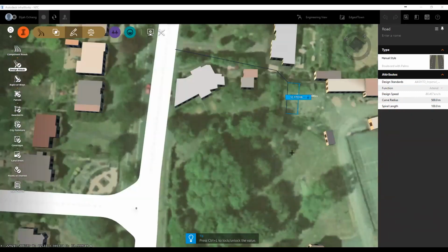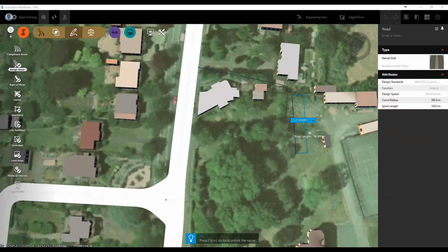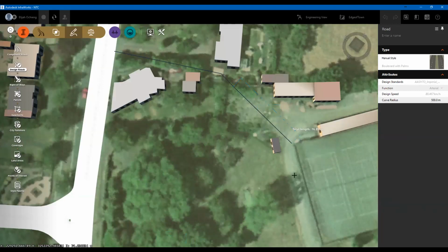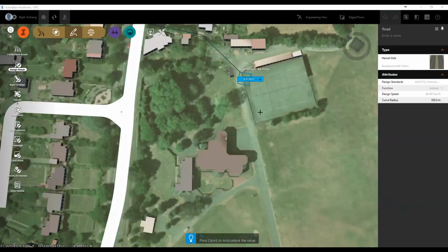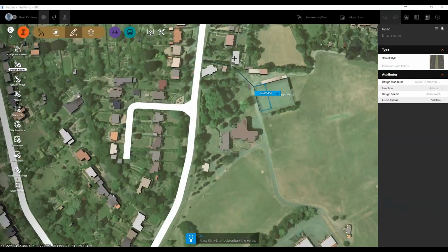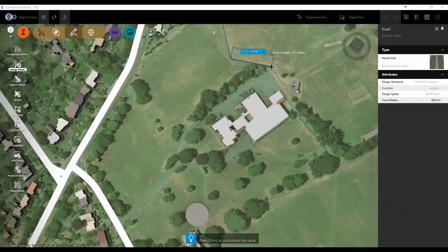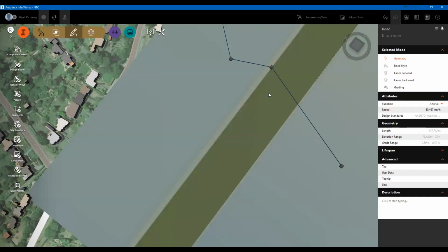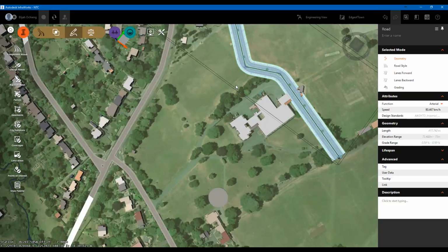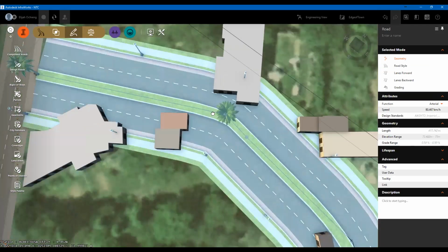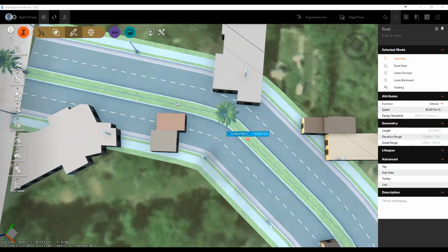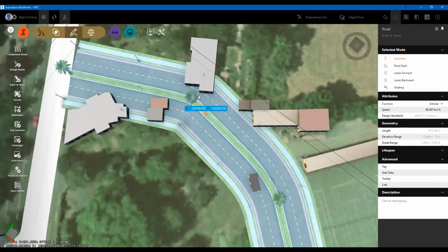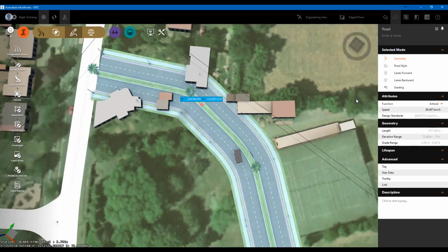At that particular point, I'll just go straight to link it up with this small component here. And I can change the type of the curve. So I can easily place the road and link it up with where none exists. I assume my road will be ending at this point. If I double click, it builds up the road and tells me exactly how that particular road will look. Since it's an arterial road, it has automatically separated into 4 lanes with a divided carriageway.